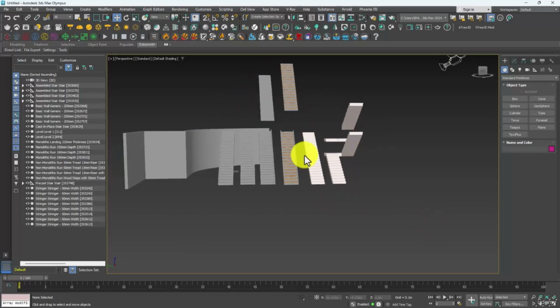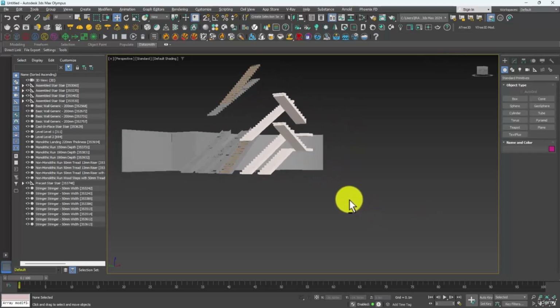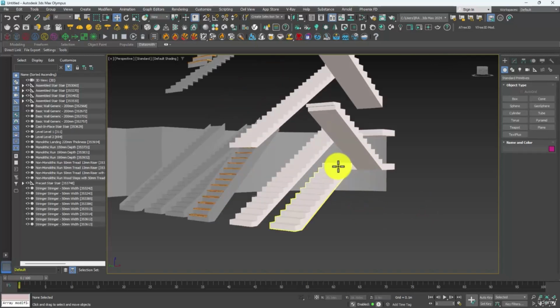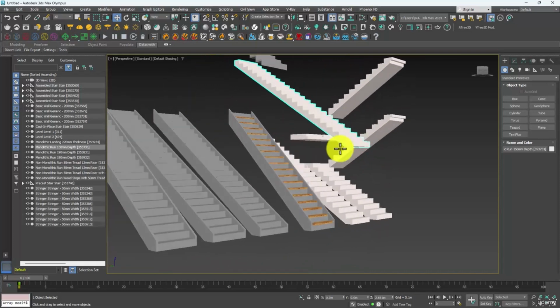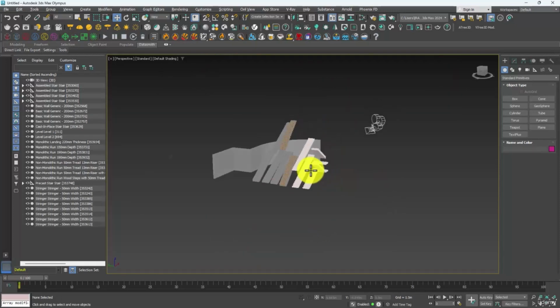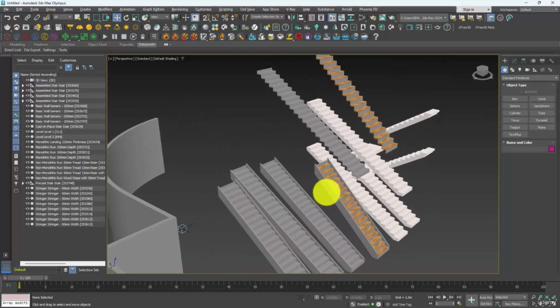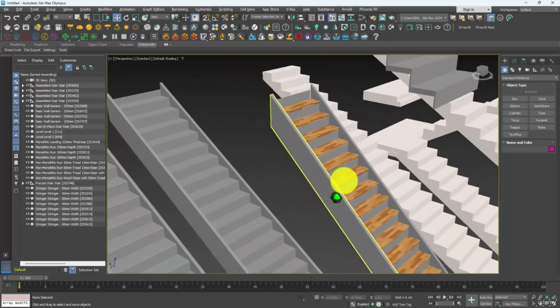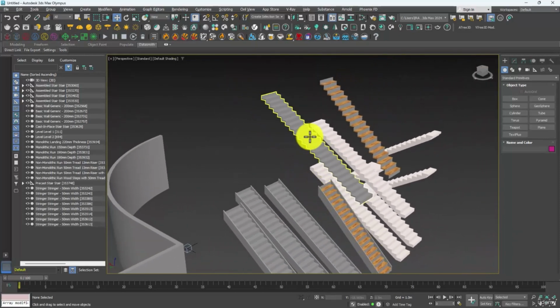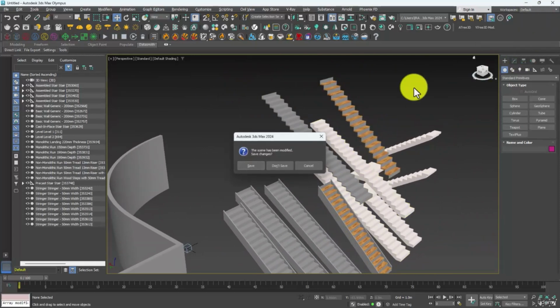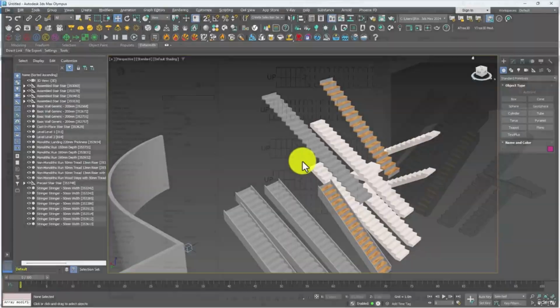In fact, when we create stairs, we got two versions, or two editions, of stairs to control the settings. However, this would increase the size of the file, but we got no solution. And this is not solved yet, still in the new versions of Revit, but we don't notice it in the display and also in the schedule table.